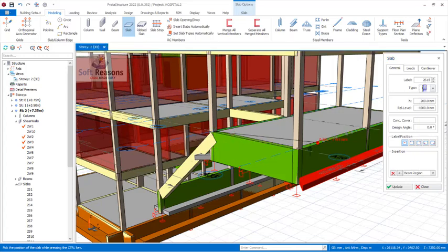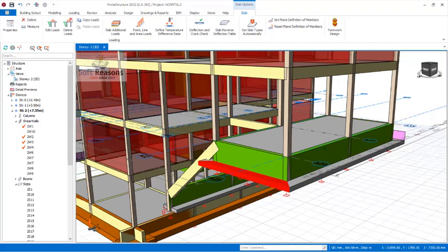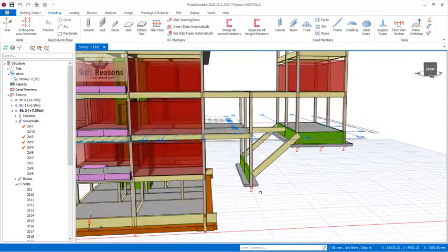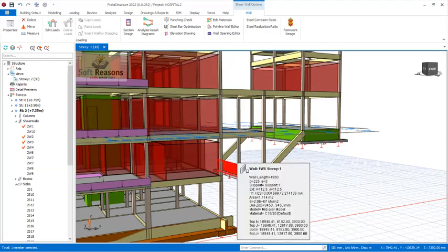So you pick the first point all the way, pick the second point, move your hand upward just like this and click. So you have it placed just like this. You can see right here. All right, so let's, for instance, we want to use an ordinary beam right here. Now what I did, the same thing applicable here. What I just showed you here is what I'm going to do in these provisions.